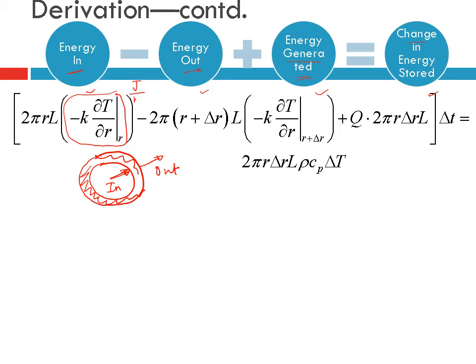So it's joules per meter square per second. Now, which meter square is that? That's the inside area. So if this is a cylinder that goes like that, it's the inside of this cylinder. So this is at r. So the surface area over which heat transfer happens is 2 pi r L.